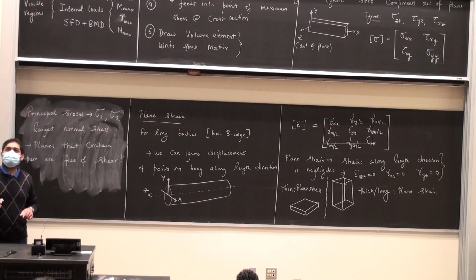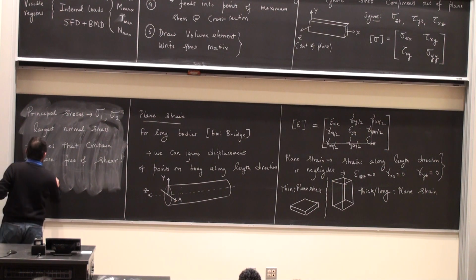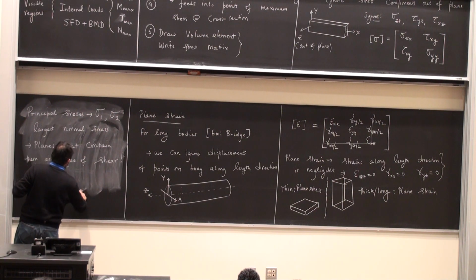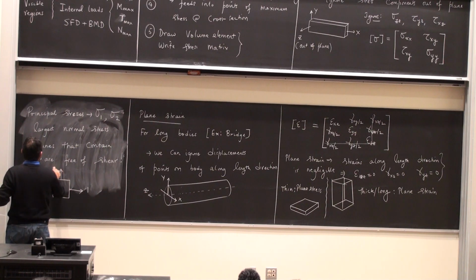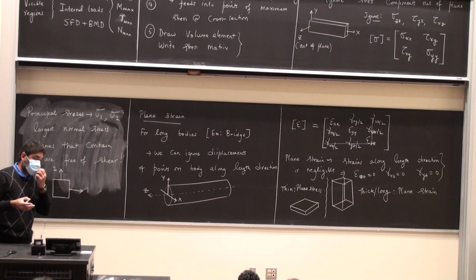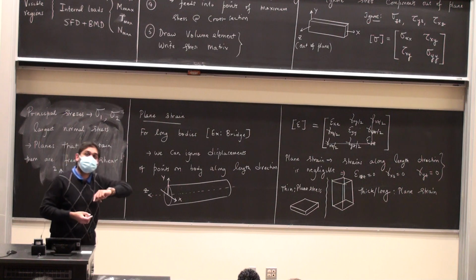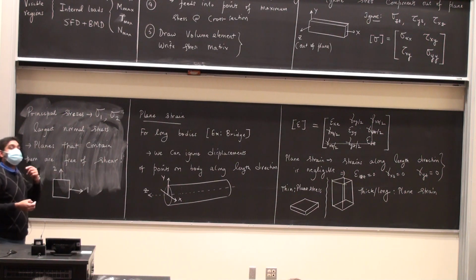And you're going to see why today. Okay, we're going to motivate the discussion. But before that, sign convention. Typically the principal directions are called the 1 and the 2 directions. There are 3 principal stresses, but because I'm looking at a two-dimensional perspective of the three-dimensional problem, employing the plane stress approximation, I'm going to see only 2 principal stresses.